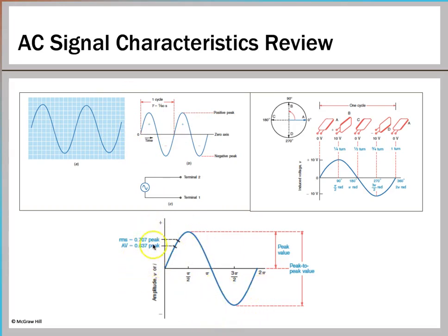The repeating signal can be characterized by a period T, and signals which do not repeat don't have a period or a frequency. So this time period is T, and frequency is given by f equals 1 by T. And there's one more term called duty cycle.